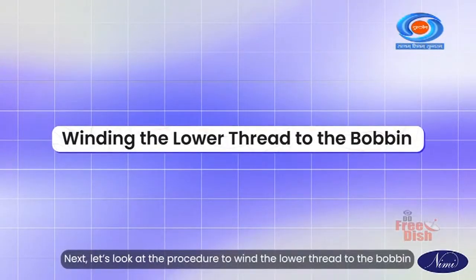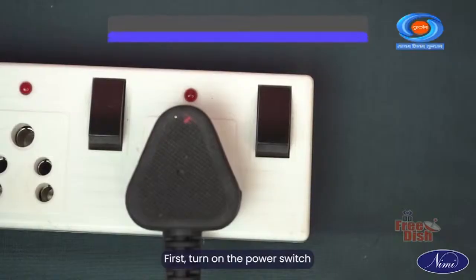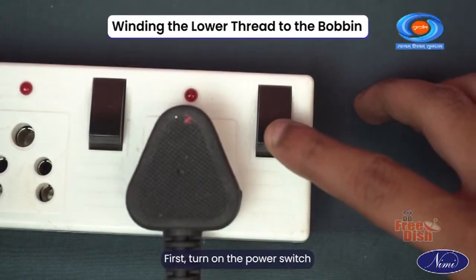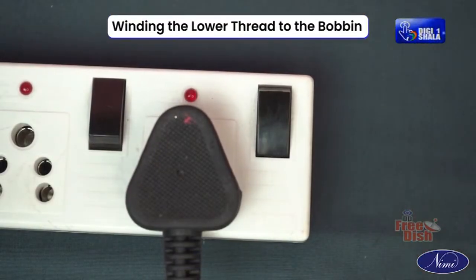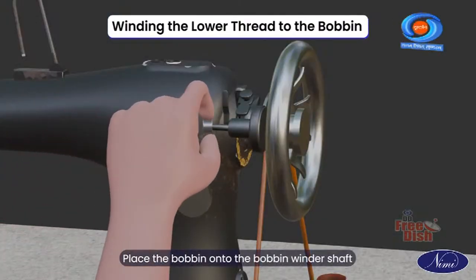Next, let's look at the procedure to wind the lower thread to the bobbin. First, turn on the power switch. Place the bobbin onto the bobbin winder shaft.